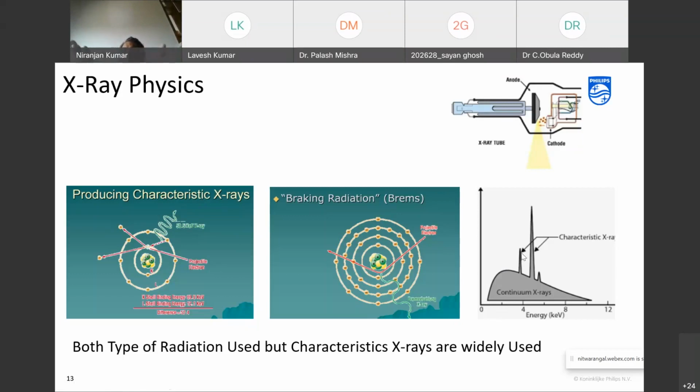It is a kind of filament control. We put a grid which blocks the electron movement, and if you are from electrical engineering, it is giving a positive voltage very near to the filament. So the electron will not go to the target, it will just go to the positive voltage very near, because everyone likes shortcuts, and electrons also like the shortcut.